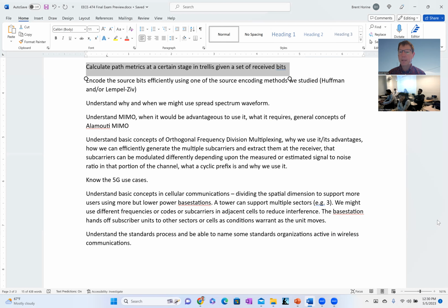And then if someone's jamming that one, we might lose those symbols. We might not be able to estimate those correctly. But if we've used some error control coding, we'll hopefully be successful when we hop to another channel and find the redundant information there, right?